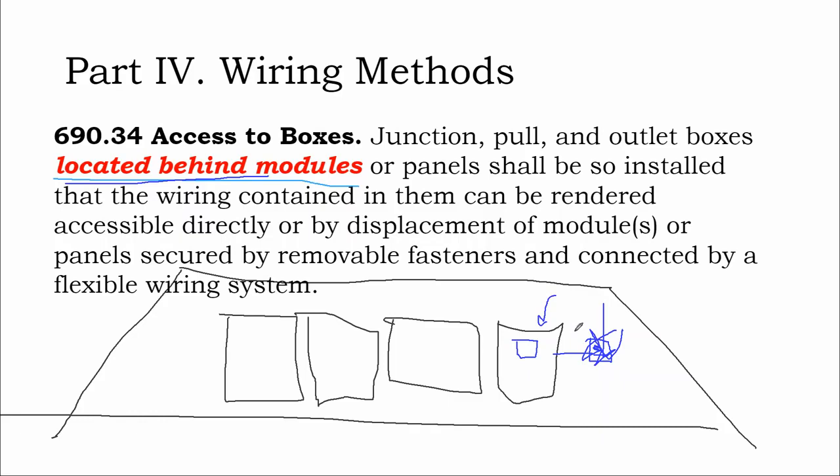You are allowed to obstruct this box by putting it underneath the solar array. And it's a matter of professionalism on whether you do this or not, because a low profile box that fits underneath the solar array is a specialty item. So only solar installers really know about like the Soladeck box. Sometimes I'll get a Soladeck box that's just an empty shell and run all the way back to the inverter. If I'm using MC cable, I'll use that Soladeck box to do transitioning from MC to the PV wire up on the rooftop. But I love hiding them underneath the solar array because then you can't see it.